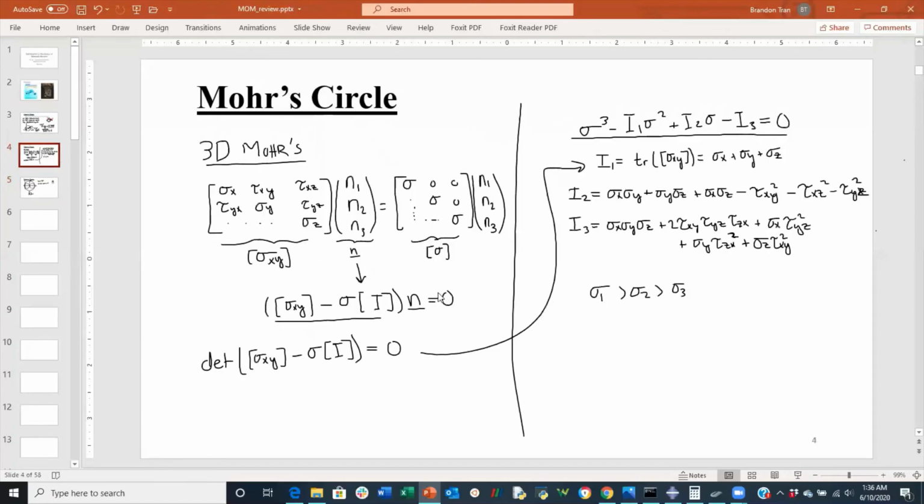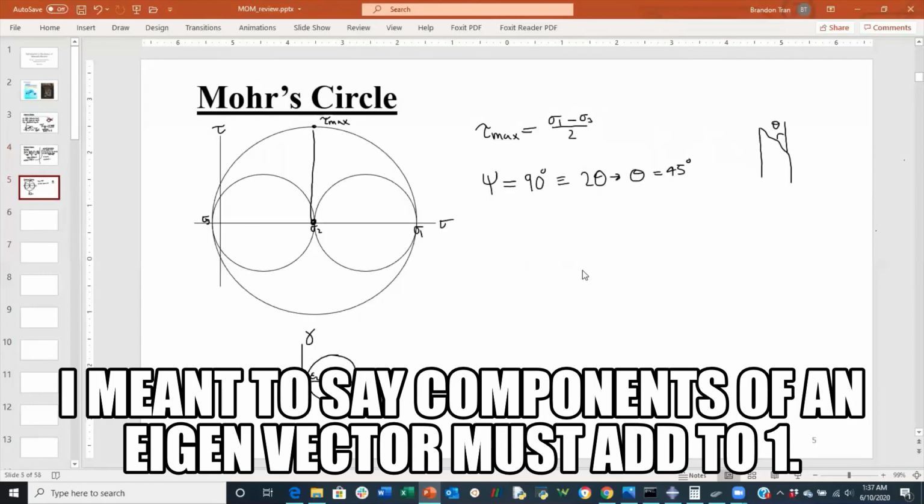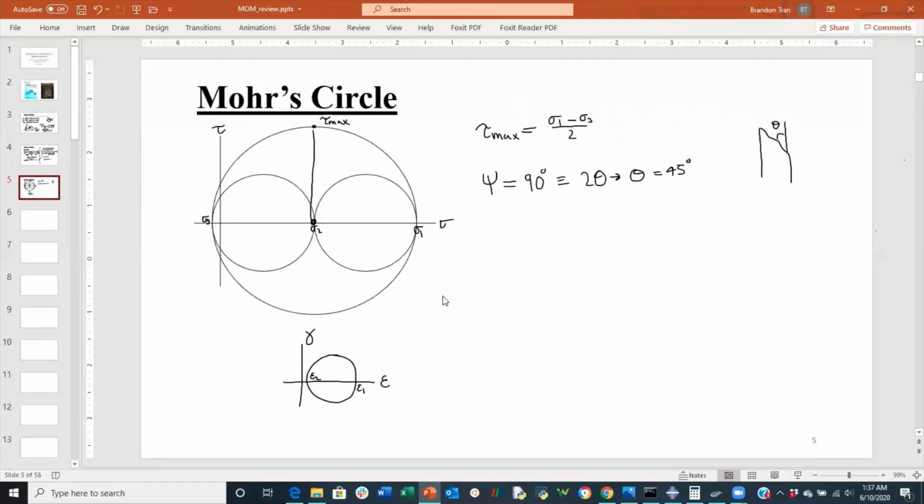So back to this equation here, once you find your principal stresses, you essentially apply one principal stress per iteration to find where your principal stress directions are. With the additional equation that you need to know, which is, let's see if I write it here, that for whichever principal stress direction you're analyzing, the eigenvector, the unit vectors must all add up to 1. Okay, so that's essentially how you find your principal stress directions. You can do the same thing with your principal strain directions.